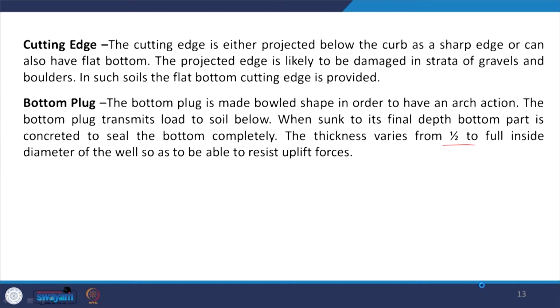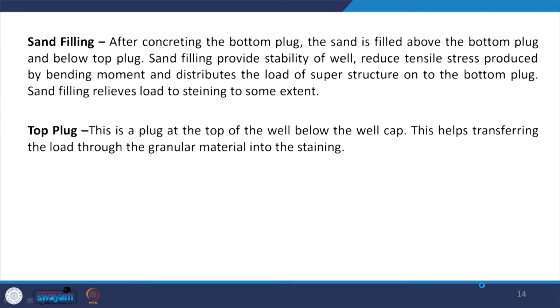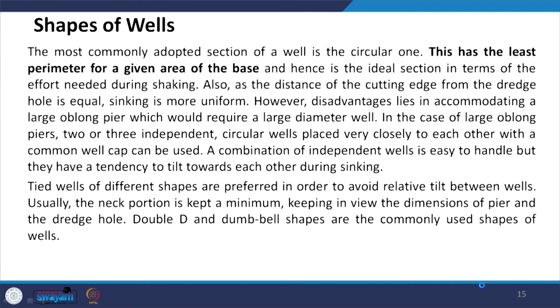Then after this you have the top plug. This is a plug at the top of the well below the well cap. This helps transferring the load through the granular material into the steining. So, this we already discussed. Now, let us talk about different shapes of wells.